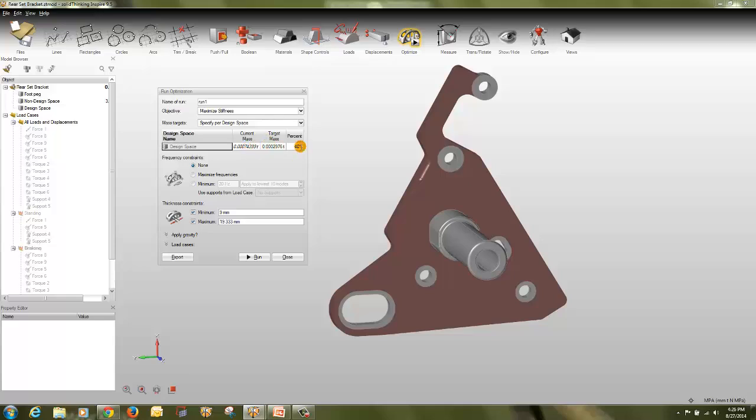So it is like current mass to target mass, you can have like 10%. You can change it, or you can put it from the actual mass to target mass if you want it in kg. It's 0.74 kg, so 10% of 0.74 is this, 50% is this. So it will keep this, the rest it will remove. So these are the options in mass targets